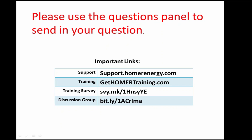The scaled parameter is simply to make it easier for you to, for example, use data from a nearby airport, but you think that the wind is actually better or worse where you are than where the data is from, or to do a sensitivity analysis, which, given how important the wind resource is, we almost always recommend that you do. So that scaling just makes it easier to do that sensitivity analysis. So there's two different things going on there.